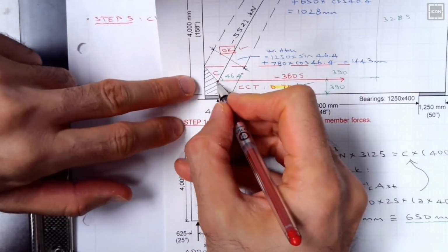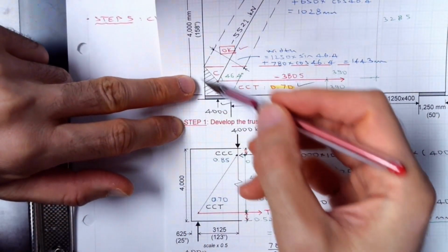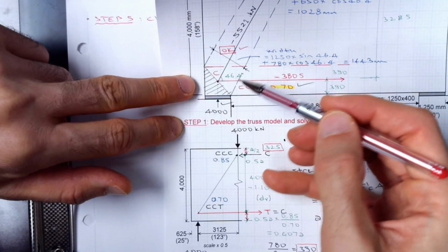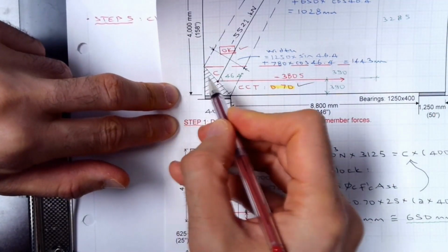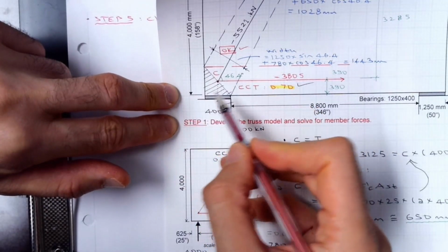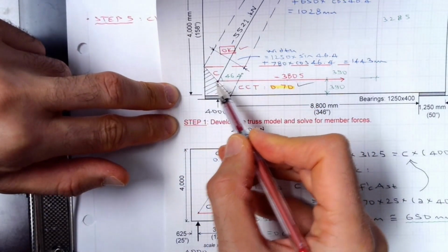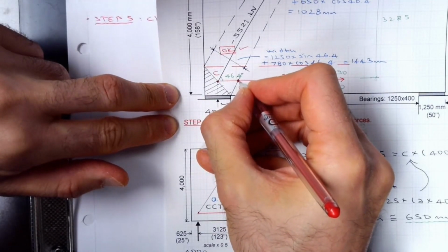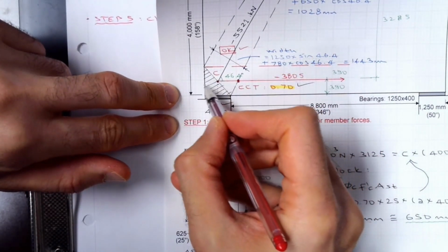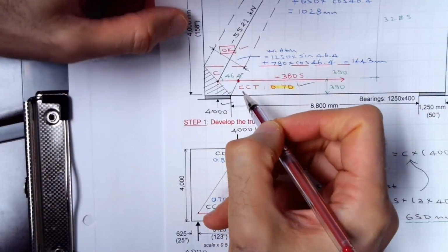And step 5, tie anchorage. I'm checking whether I need a hook or not. Sometimes the view is deceptive. Sometimes in the previous example, it looked like we had tons of space available, but it needed a hook. But this time, it looks like we have a very short distance. It may not need a hook. So I'm going to be checking it at this point. This is my available distance, so I'm going to be checking it with regards to the required length.